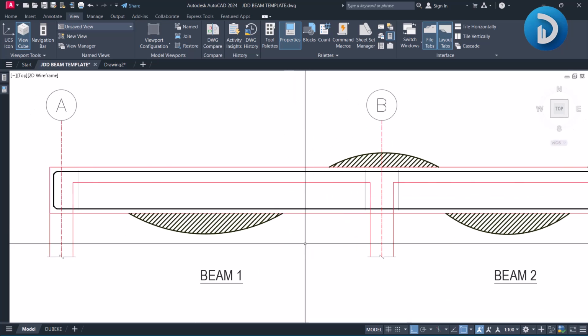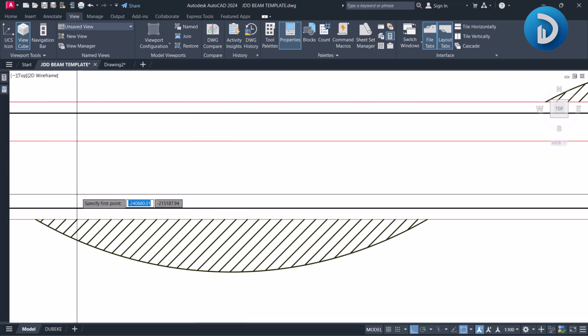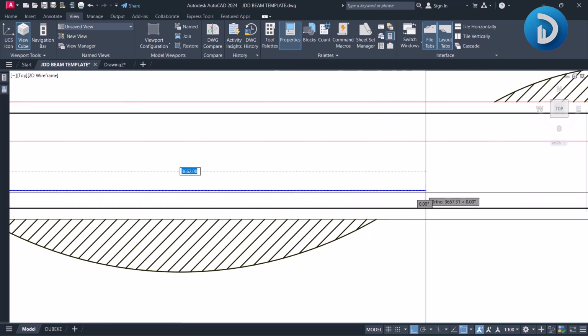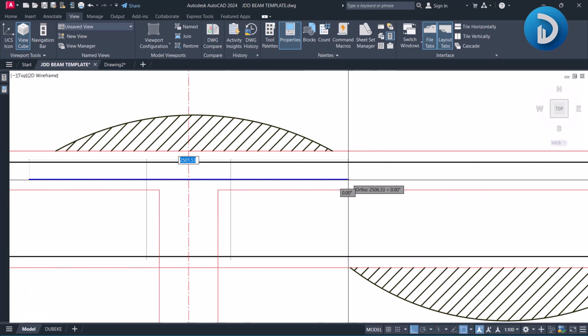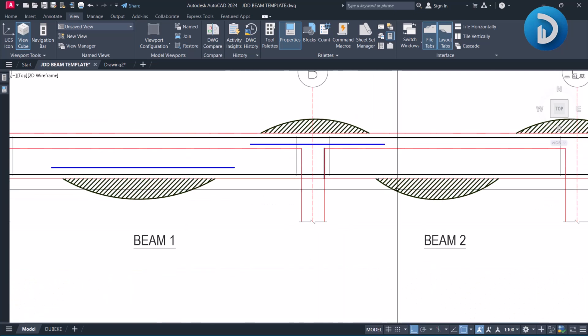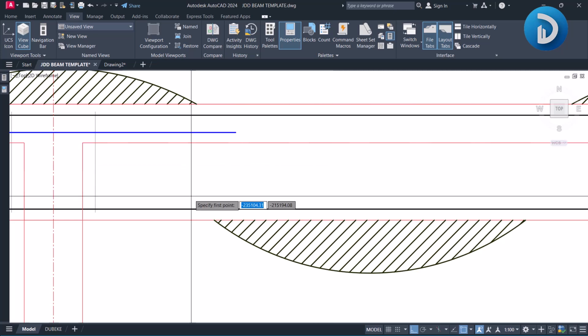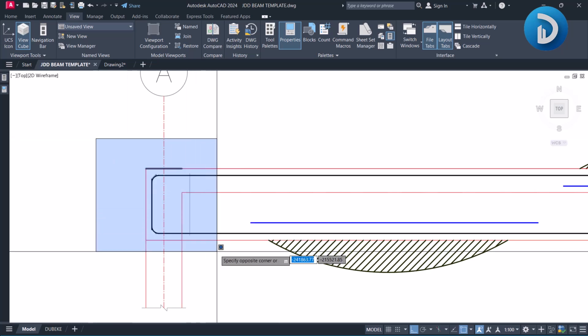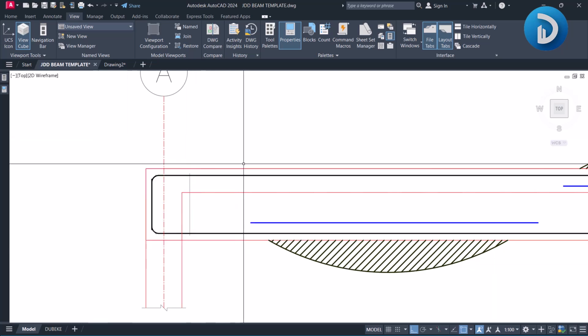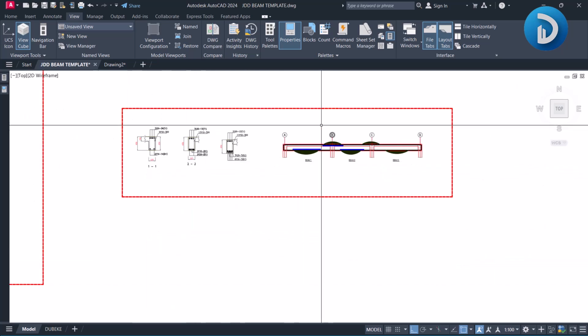So in turn, we should be having higher reinforcement at the bottom in this section, while higher reinforcement at the top when we get to this section. So this is an ideal scenario. Then for this part, it all depends on your fixed end condition.